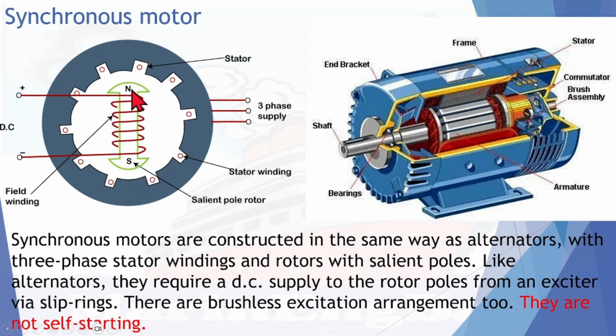the less difference between this stator magnetic field as well as rotor magnetic field. In that condition, there's a possibility the stator and the rotor, with different polarities, lock together, and thereafter continue to spin to maintain the spin. So that is how a synchronous motor starting takes place.